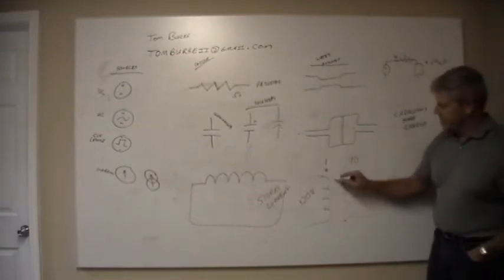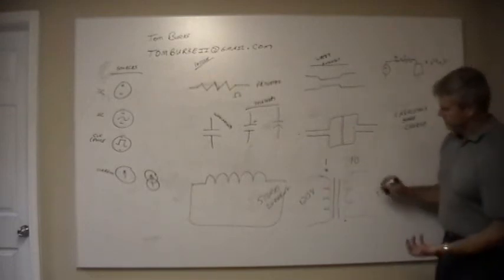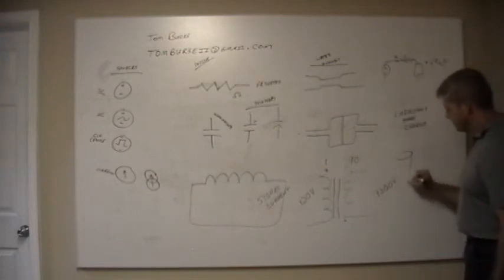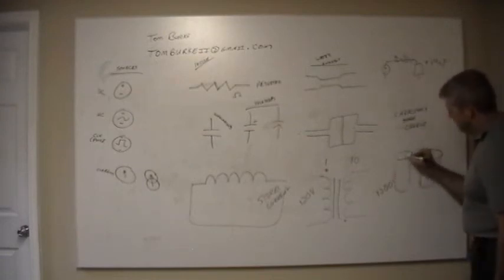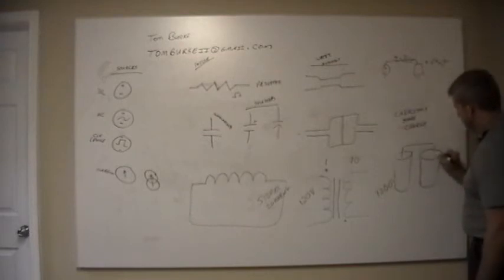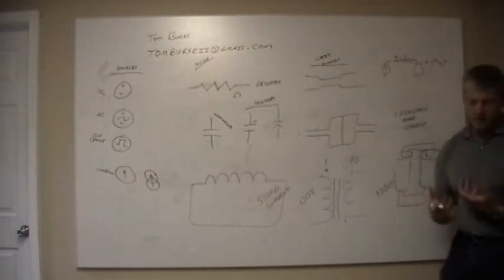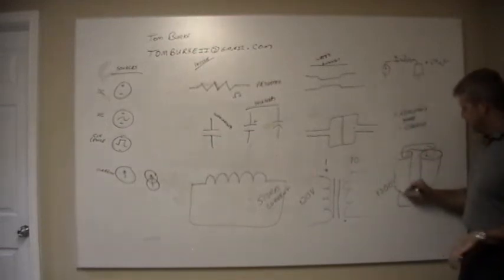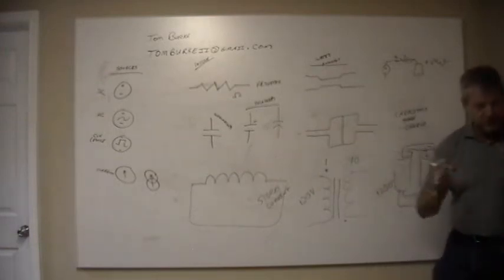You know, these on real transformers are often iron, laminated iron, and big cores that physically, if you look at them, you've got one coil set up sort of as a cylinder here, and another coil set up sort of as a cylinder here, and then the transformer itself, that core goes through like this because the metal directs the magnetic flux and keeps it in here. When you've got no air, it just kind of goes everywhere. You can't focus it. The core focuses it in.